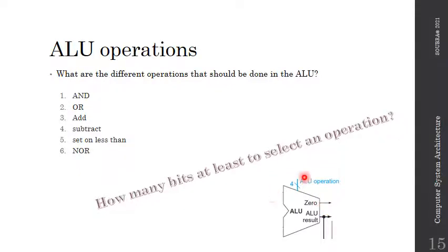Now, another typical exam question of mine. Here, with 4 bits, we could have up to 16, so we still have 10 possible here. For some reason, 5 years from now, someone said that I need 17 operations of my ALU. Well, what should I change in order to be able to have 17 operations? Well, all I have to do is add an extra bit.